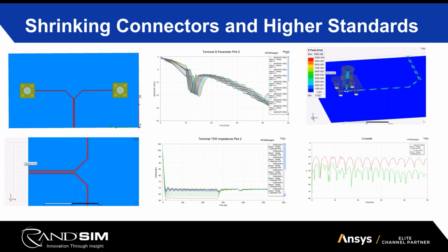Looking at S parameters is not the only thing that HFSS offers. We can also look at the electric field, among many others, and see how it's actually moving across our board. This is useful for seeing how the signal is moving through our traces in the PCB, as well as helpful in identifying any areas that may be problem areas.